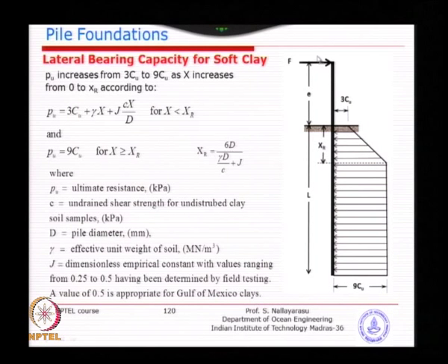So, you can easily understand that when you apply a horizontal load, when the pile is trying to push, the soft clay will start squeezing up, and that is where the remolding will happen. Once the soil like soft clay gets remolded, it loses its strength. So, that is why you have a reduced strength at the top. For offshore piles, like what I was explaining in the previous class, they are mostly long cylinder steel pipe piles, and that is why you will see that the pressure distribution or reaction from the soil is almost going to be continuously uniform until the point where the pile gets full fixity. After that, the influence of the loading on the pile and the soil is going to be minimum. So, that is the concept adopted.